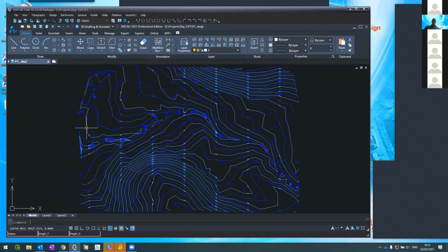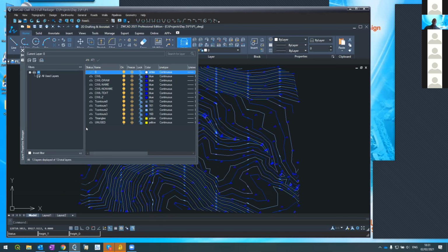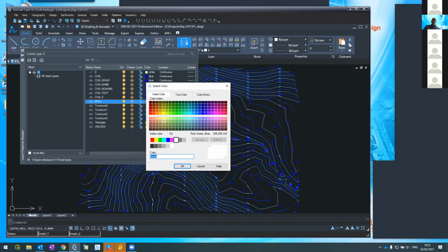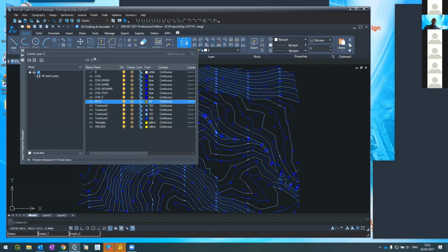What I'm going to do next, I'm in the ACAD, I'm opening a new layer and I name it CL, my center line. You can name it whatever you like. It's not so important as long as you remember. I call it my center line. I give it a color, this, and I make it the current layer.